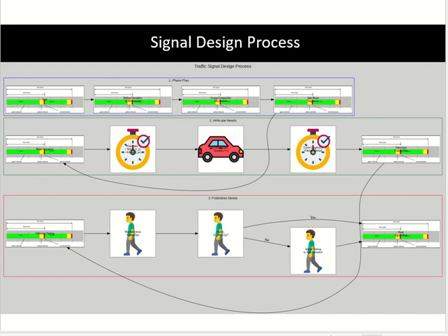Okay. So after the phasing plan, you decide the lanes for which you are designing critically. You call it critical lane. And for that critical lane, you need the critical lane volume. So all the rest of the calculations are based on the critical lane volume. The remaining volume is negligible. You can ignore it.